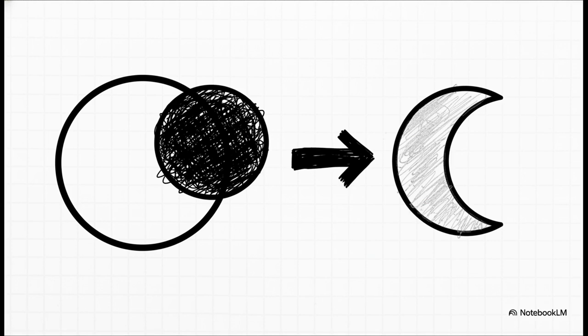Once you've got your basic shapes on the board, you manipulate them using Boolean operations. By mastering just 4 core operations, you can combine simple geometry into incredibly complex custom UI elements. Union is pretty straightforward. It just merges multiple elements together into one continuous shape. Intersect creates a new shape exclusively where your original elements overlap. Exclude does the exact opposite. It removes those overlapping sections entirely.